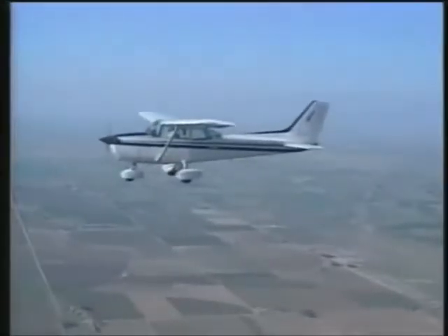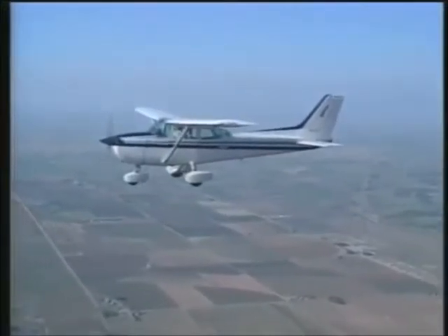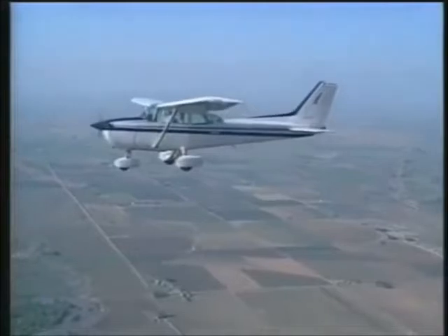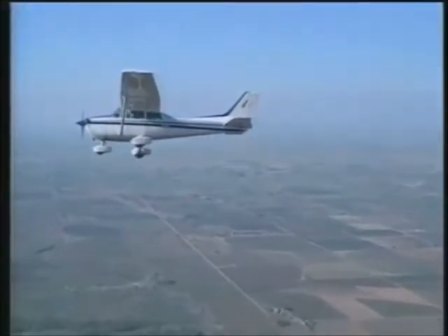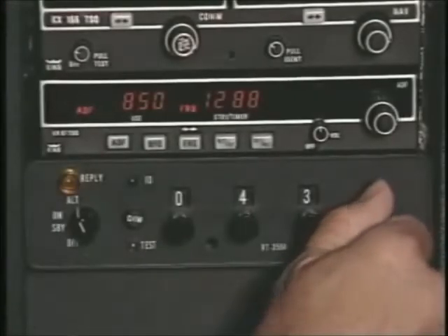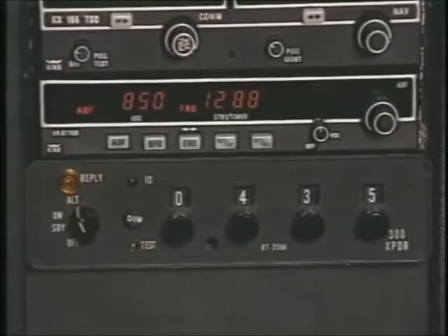If the controller uses the words, aircraft calling Jensen Approach, stand by, radio communications have not been established, and you must remain clear of the Class C airspace. In most cases, the controller will give you a transponder code and ask you to ident. Cessna 740, radar contact, 23 miles northeast of Jensen, turn left, heading 220 for left base, runway 17.